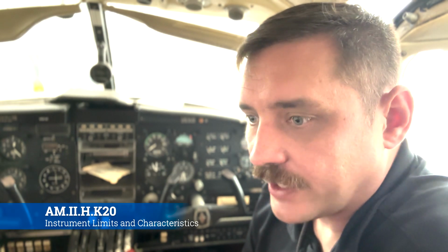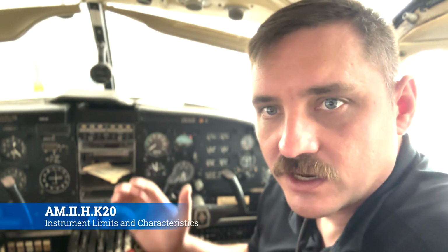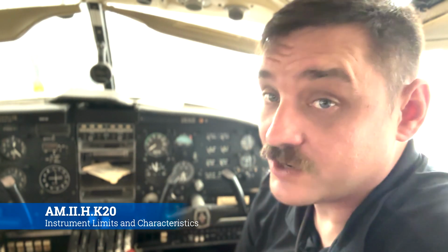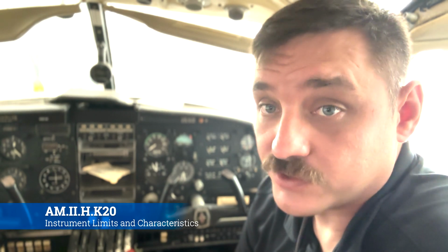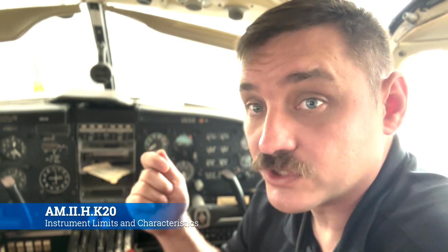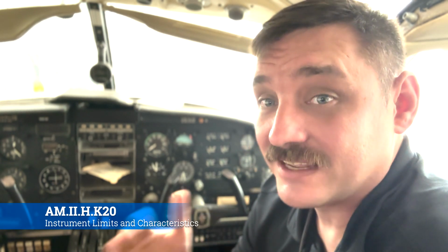So if you have a high engine oil pressure, then you need to figure out, okay, is that engine oil pressure really high, or do we have a transducer that's bad, or is there something else? The way that we do that is we put another transducer in there and then compare and contrast. If we know that this transducer is good, and we put that in there, and we still see the same indication, that at least means that the system itself is what's causing it, not necessarily the transducer.